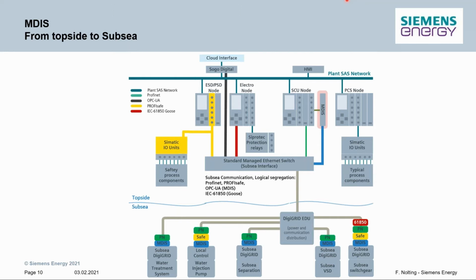Also alongside Profinet and ProfiSafe, so that we have all the benefits of the different protocols right on the seabed. And that enables us to use the same tools topside, program it, document it in the same way as we do topside. That's no different for us if we are going subsea or vertical or horizontal. And we are also able to use really SIL-rated I/O subsea from topside, actually encapsulated for subsea. So that means we can really run safe applications.